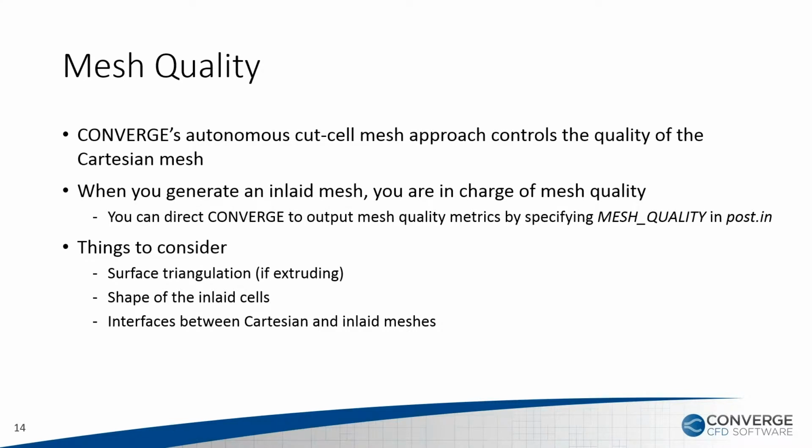So now that we've seen how to create the inlaid mesh in Studio, there are a few things that we would have to keep in mind when we're generating the inlaid mesh, and that's with regards to mesh quality. Typically, when you're just using CONVERGE's cut cell approach, CONVERGE takes care of the mesh quality automatically. But when you're generating the inlaid mesh, you need to be careful when you're creating it so that you end up with a good quality mesh.